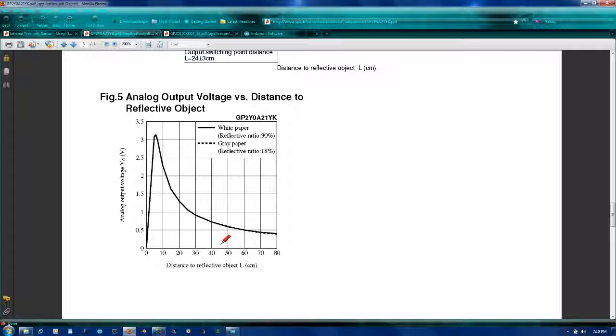So you see the distance here, and the voltage translates into numbers between 0 and 1023. I think we'll review that, not in this tutorial. I believe the sonic sensor is actually more linear. But in another tutorial, we'll review how you come up with the numbers for this.